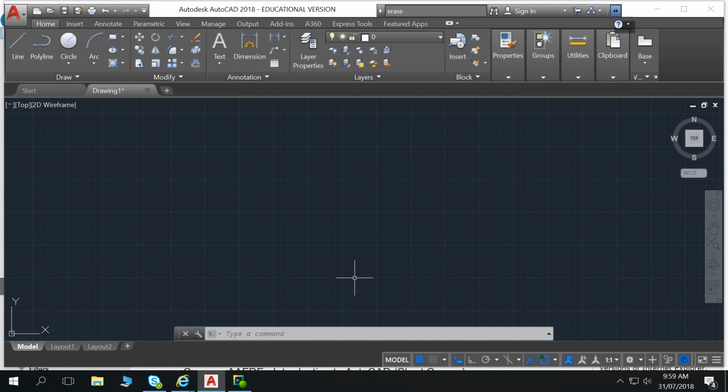Okay. So this part here, as I told you, is your drawing area, the AutoCAD, this whole thing's called the AutoCAD interface, but it's seen as model space. Then if you go down below here, this is your command line, all right? This shows you what either your last command was that you did on your drawing or what is to do next. So it will say specify line point, which you do.